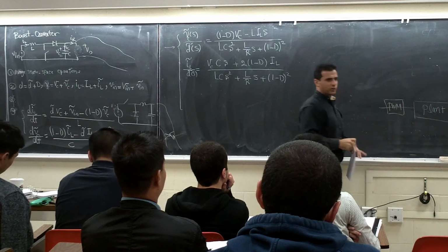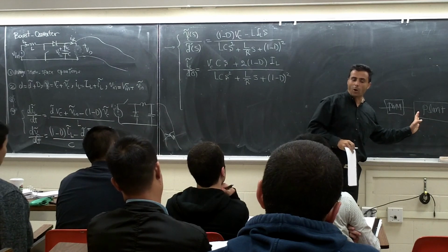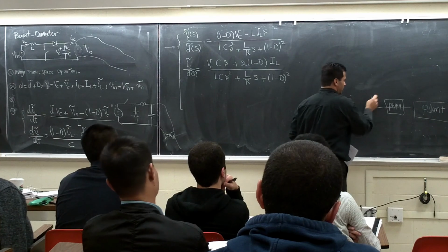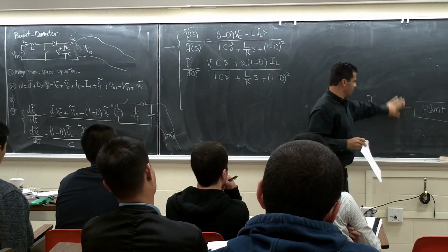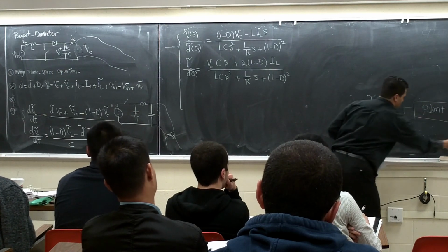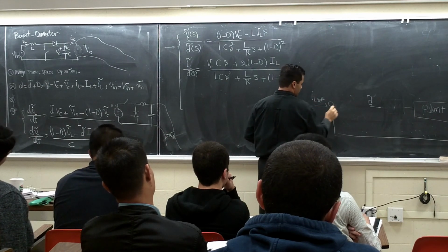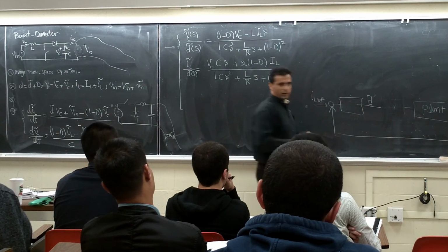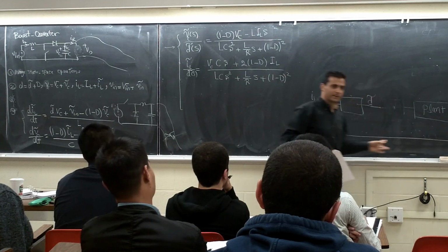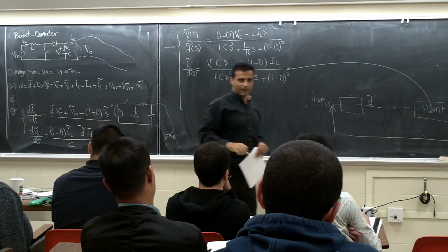The PWM generator is nothing, just changing the average value to a pulse, so you will be able to switch your switches. But you have a D coming here, so basically you can get rid of this one. You say D is coming, I'm going to get IL, and this one is going to go to my feedback loop, with IL ref, controller and plant. This way I can control my current. This transfer function is this.